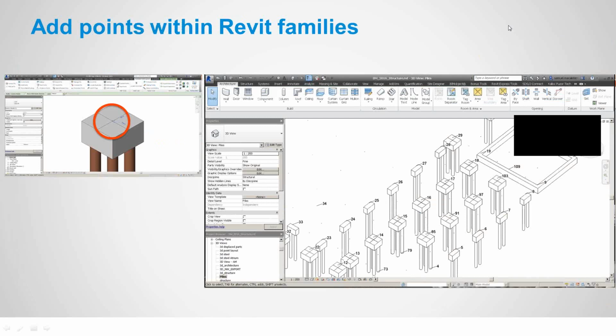Another way to do this is to actually do it in the family of Revit. For those of you new to Revit, it's parametric modeling of objects, with a lot of intelligence in these objects. These are the families. What you can do is open up a simple family, which would be these metal piles with pile caps. We may want to have a control point on the center of those pile caps. So we can open up that family.